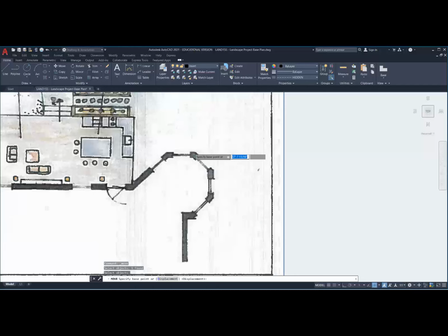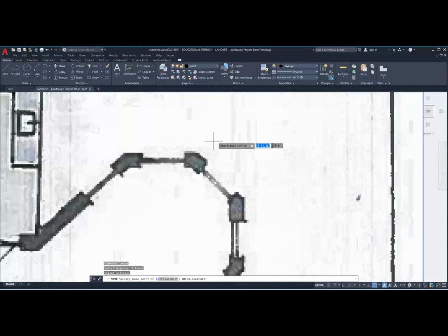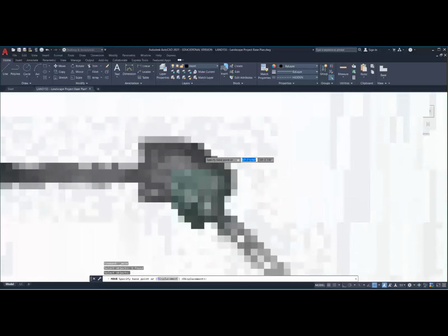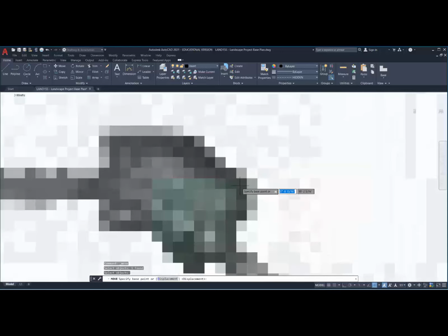How do we know we're at the pixel level? We'll see the squares. And that's really what's critical here, is that we start seeing the squares. And this identifies that it's a raster base or a PDF type of file. So you'll notice these squares, they're kind of all over the place. They're not one solid color. So I want to pick the thickest region of the darkest color, which is this group of 4, and I want to pick the corner. So I'm going to go right into this group of 4 and click.